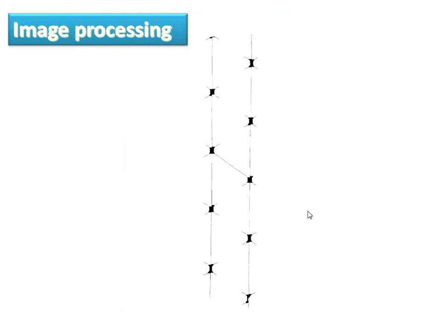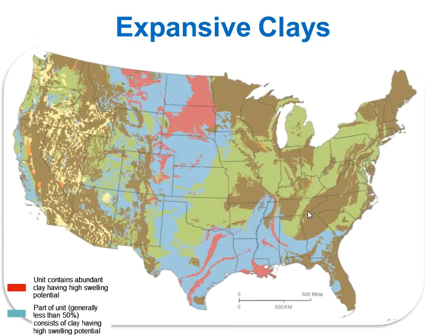And we're playing with digital image processing in order to manage this huge volume of data. We want the bending. We are trying to capture the bending of the transverse ribs in order to translate how that bending relates to the load that is being carried by that node. We also need the rotation of the joints, if any. We also need the stretching of the ribs. We also need the scatter of those displacements. But that's beyond TxDOT. TxDOT is not interested in that so far.